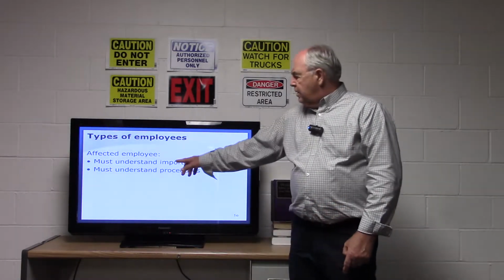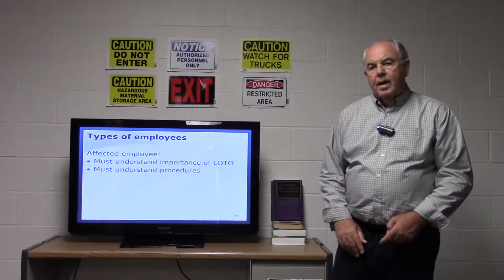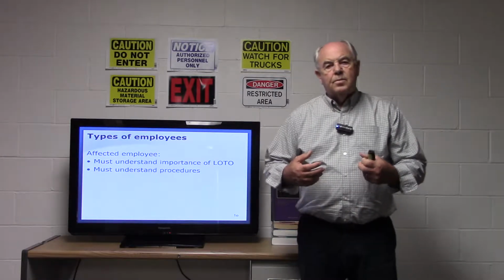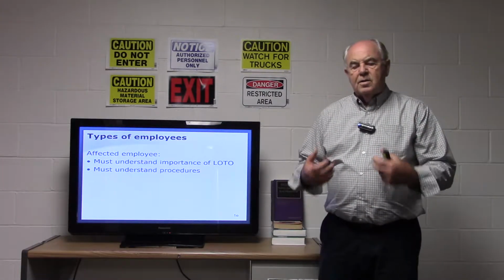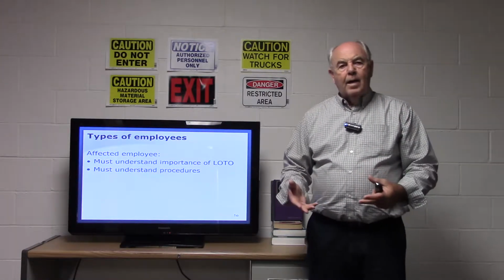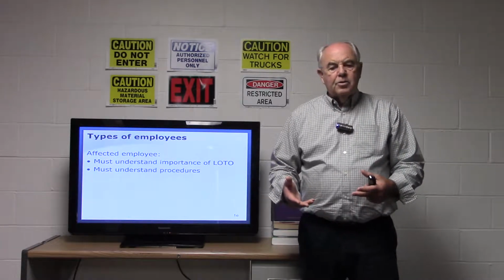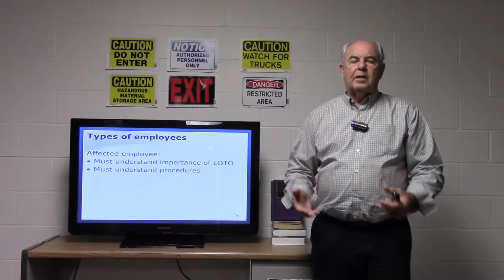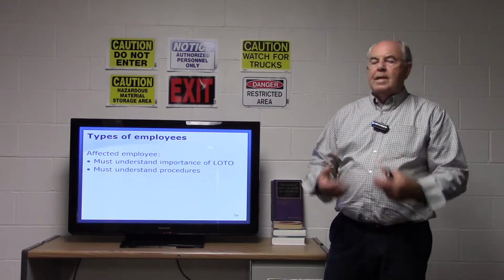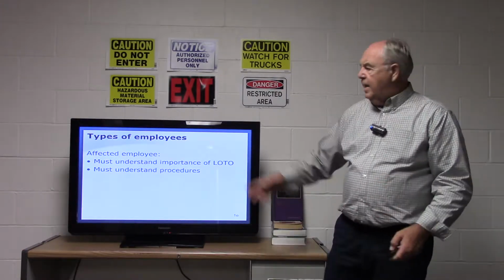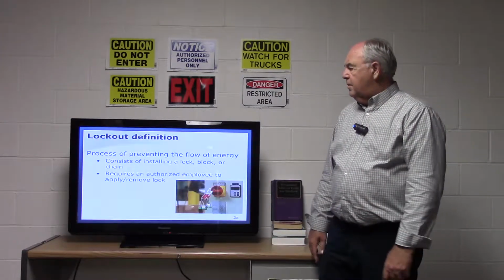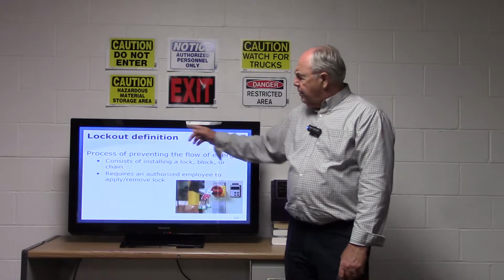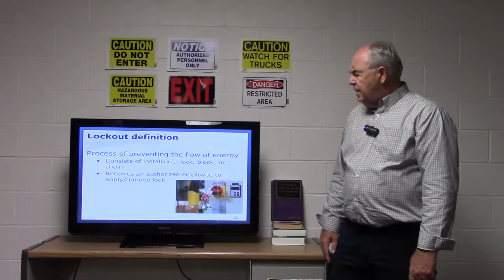Affected employees must understand the importance of lockout tagout, understand the importance of the procedures, understand what they're seeing when they see a lock or a tag on a piece of equipment, and understand they must not operate or try to start that equipment or even attempt to move a lock or a tag once this has been placed on a piece of equipment. Now we talk about the lockout tagout definitions.